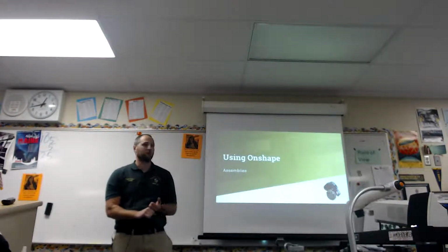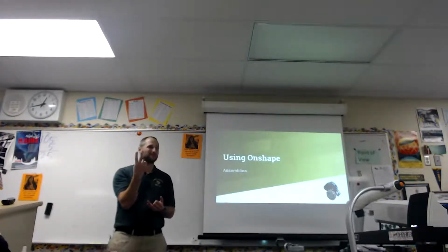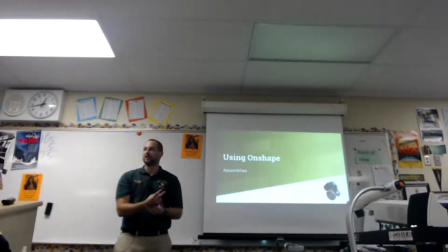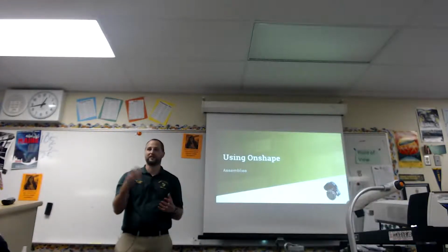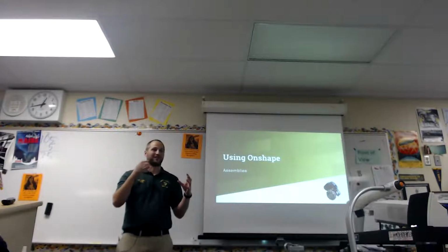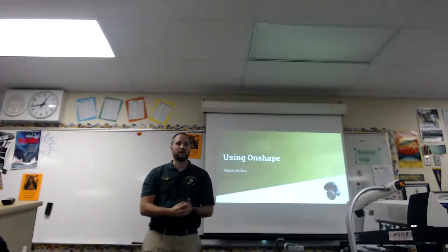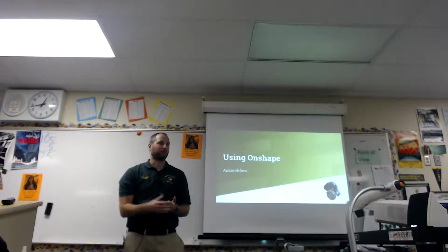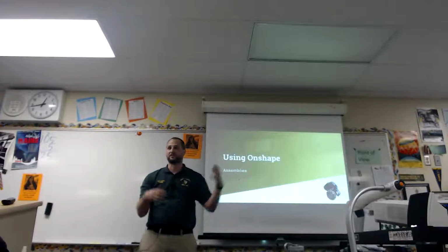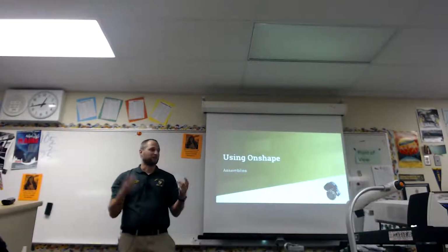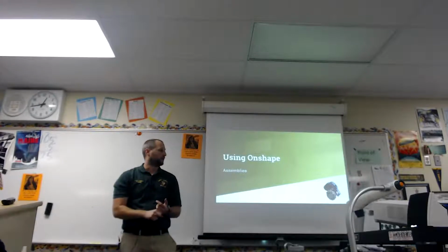Another advantage to Onshape assemblies is that they happen with a single mate connector. Sometimes you can use two to make your life easier, but instead of building out different flushes and mates, et cetera, where when you change your geometry, now you have 3 different points of failure, everything's based off one piece. They call it a mate connector, and they pop up pre-populated all over parts as you build them, based on center of gravity or geometric centers, corners, et cetera. But also you can drag and drop them, just create them anywhere you want.